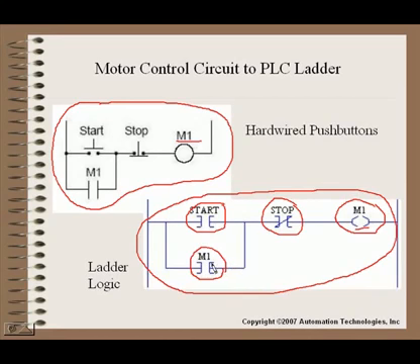Now, actually, I don't like to do this. This is not where we like to stop. We like to take this relay coil, take a contact that would come back from that relay coil and then enter that into our PLC program. Therefore we have a real-world understanding when we seal our circuit in. If this relay were to drop out for any reason in the field, then it would also drop our seal in the program.